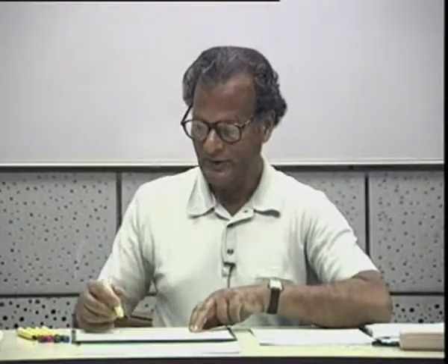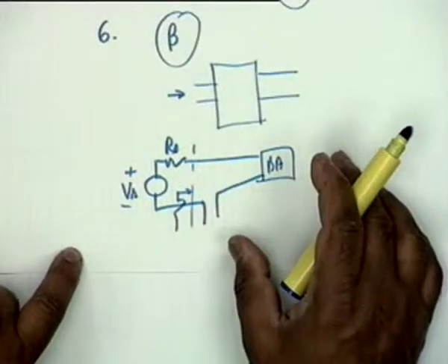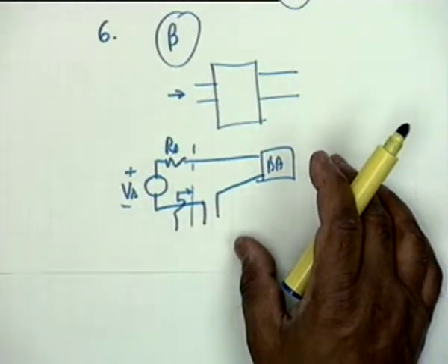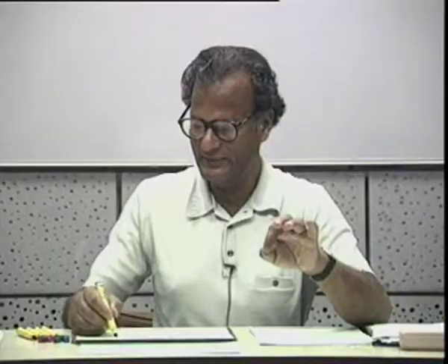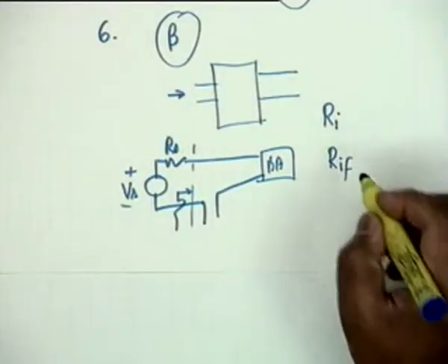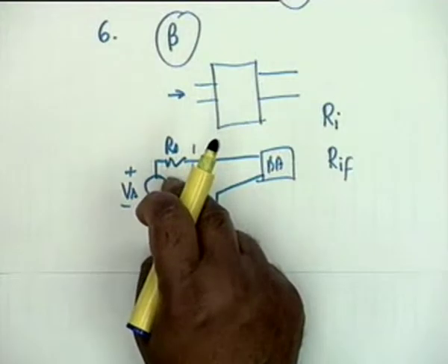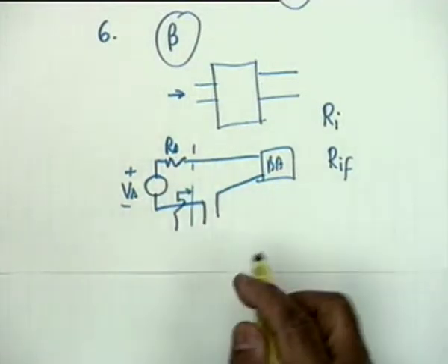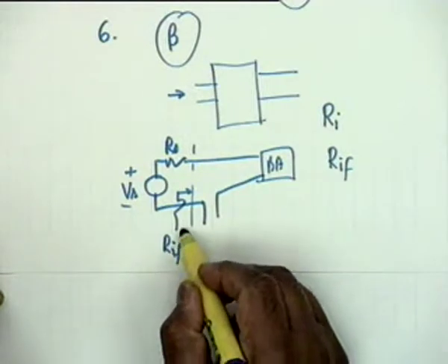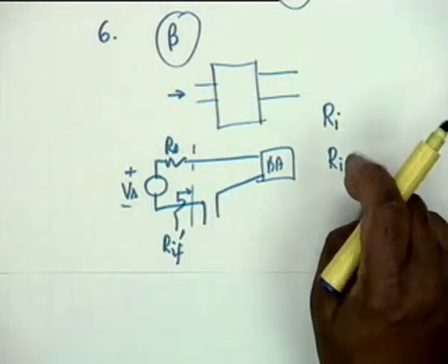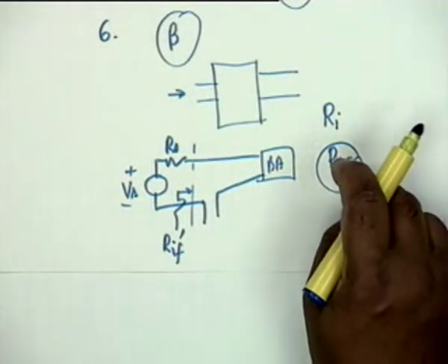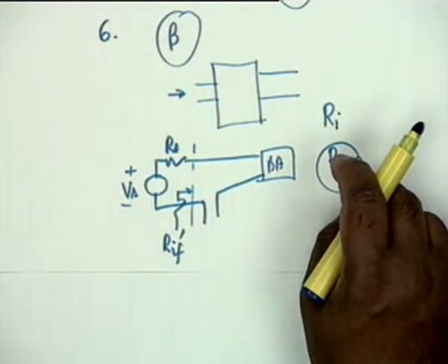When I absorb Rs in the basic amplifier, obviously Rs is inside, and in the feedback amplifier what you find out is Ri without feedback and then Rif, both of which involve Rs. Therefore, to find out the actual input impedance faced by the source in the total feedback configuration, you have to decouple the Rif that has been found out from its Rs component.